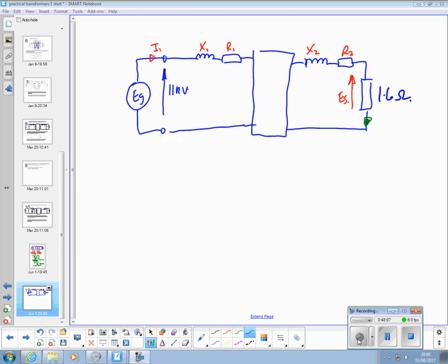This technique that we looked at earlier, transferring impedances, we're going to find the value of these secondary impedances there, and there, when they're transferred over to that side. We need to do that to do our analysis, because we don't know this voltage here, because there's losses in that side. So we can't analyse that transformer like that.